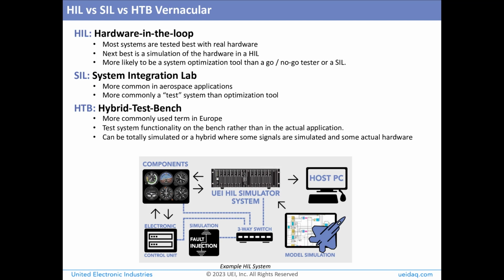We can safely state that an embedded system is best tested with real hardware under real conditions. However, most times this is very expensive, both in time and in cost. So the next best solution is to simulate the hardware with a model and use that to exercise the system, or to test with a mix of real and simulated hardware. This can help with the test coverage, since the parameters can be easily changed in a model to a value that should never be seen with real sensors and hardware.